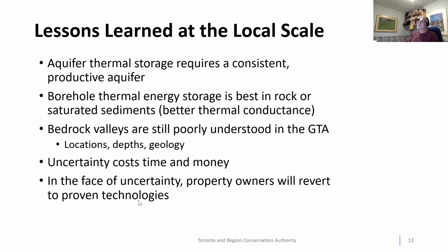So what did we learn at the local scale? For thermal energy storage, we need a consistent productive aquifer. We recognize that borehole thermal energy storage is best in rock or saturated sediments, as you get better thermal conductance. And we also learned that bedrock valleys are poorly understood in the GTA, despite all the holes that we've been poking in the ground over the years.